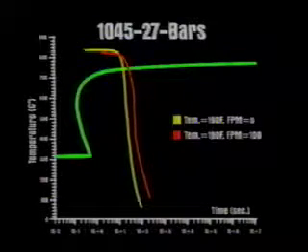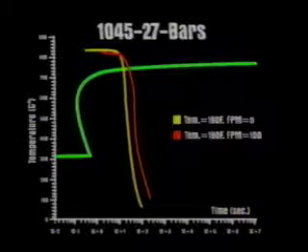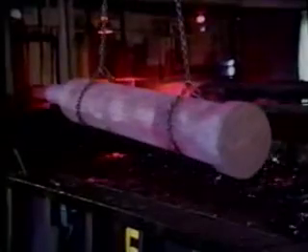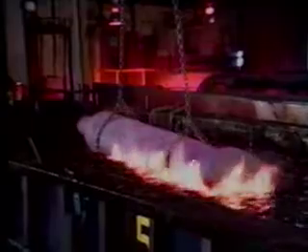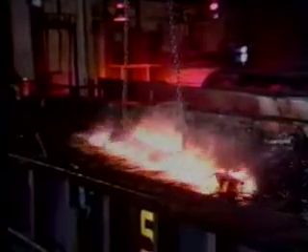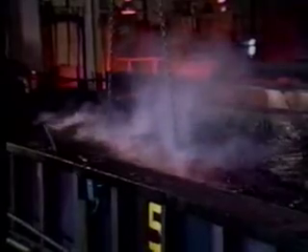This is illustrated by comparing the effect of agitation on the hardness of AISI 1045 steel when quenched in a fast oil. As expected, hardness improves with increasing agitation. Fluid flow variation in tanks may lead to variations in hardness, increased distortion, and possibly even cracking.